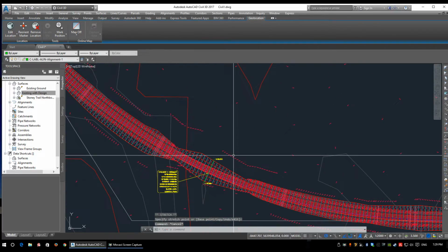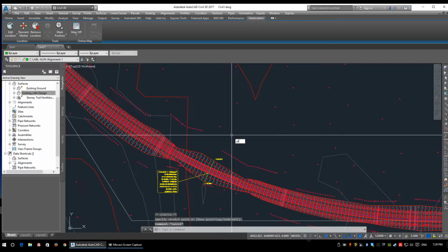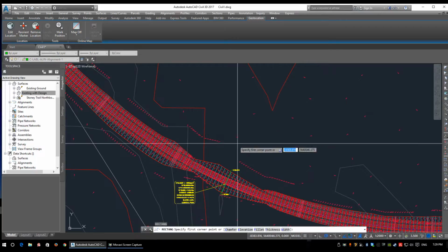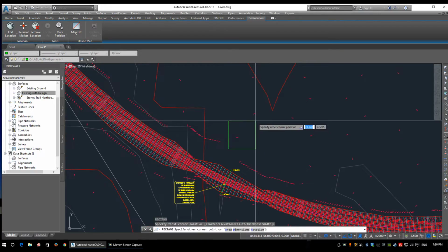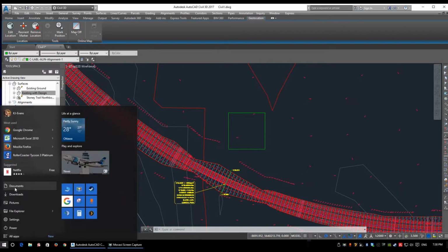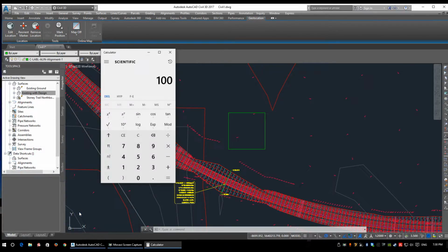So first of all, we're going to generally lay out an area of a pond. So I'm going to use actually a quick rectangle so it can make square. And I'm going to make it dimensions of, we're just going to go 100 by 100 for now. Now, doing this 100 by 100, just some simple math. We can open up a calculator. 100 times 100, 10,000 square meters. So if we design the pond to be 1 meter deep, this is going to hold 10,000 cubic meters.